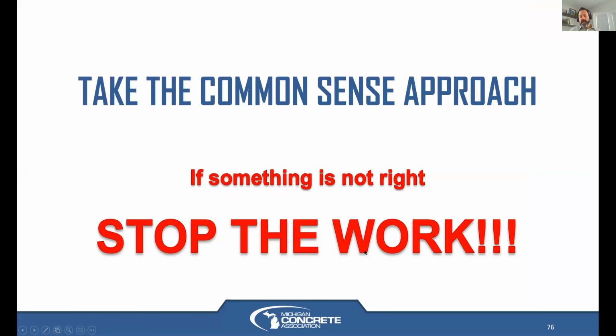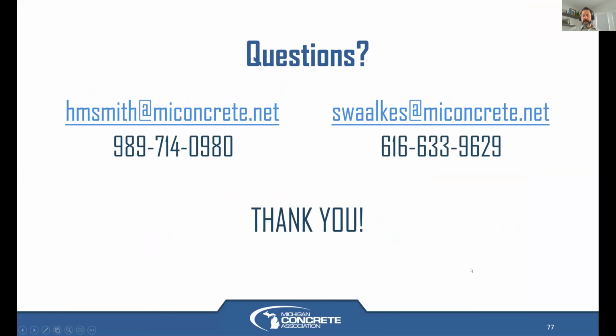So hopefully that makes sense. We feel it's common sense. If you see something that's not right in the plans or out in the field, just make sure you tell somebody. Stop the work and talk about it before the concrete cracks. So that's what we don't like to see: cracks. I know a joint is still a crack, but I'd rather see a nice straight joint than a crack in our fresh concrete.